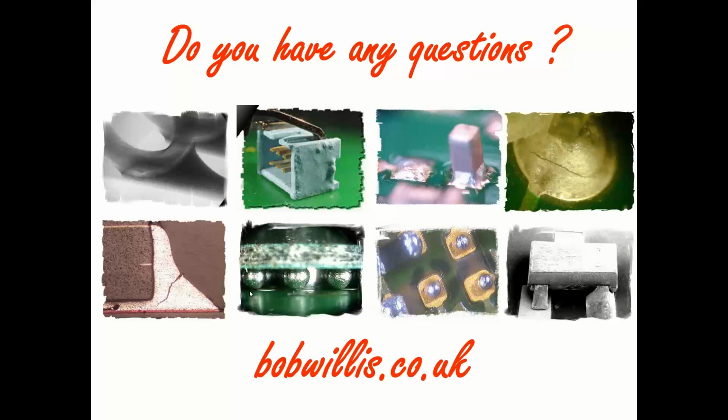But it's doing something, because so many customers, when they talk to a contract manufacturer, don't give them clear guidelines. They may say, I want it to IPC, and then when you get a couple of droplets of conformal coating, let's say on top of their logo on the board, they get upset about it. Come on, it doesn't matter.